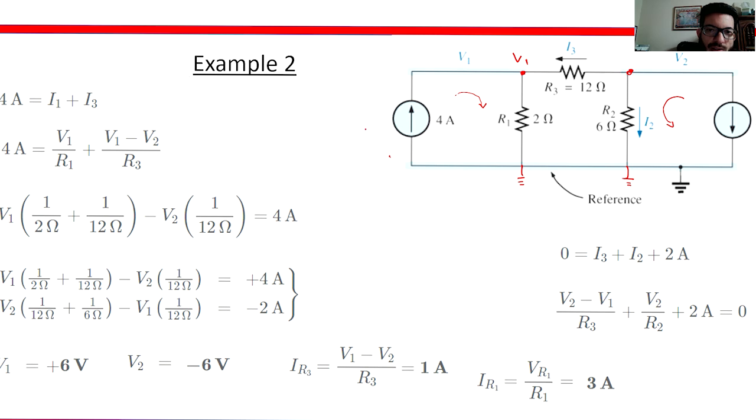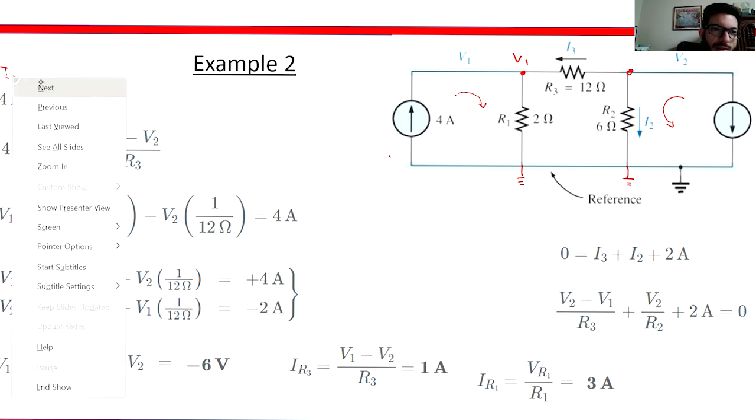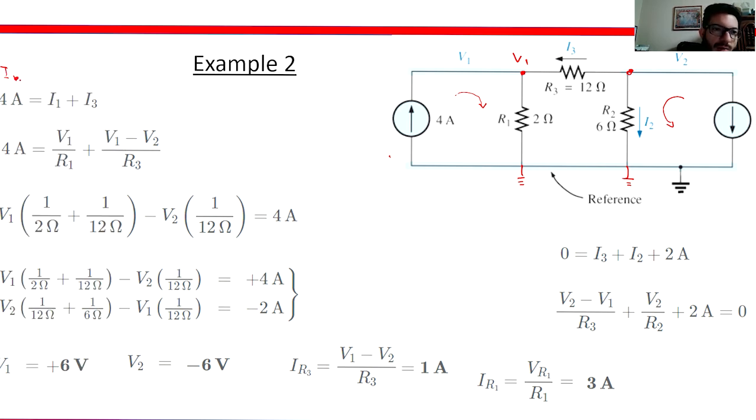So we're going to have that I1 equals, oh, they're calling that I. So I not, or I prime, whatever you want to call it, equals I1 plus I3, which is this current and that current. Good. So at V1 we have I prime, I1, I3. I prime is 4.